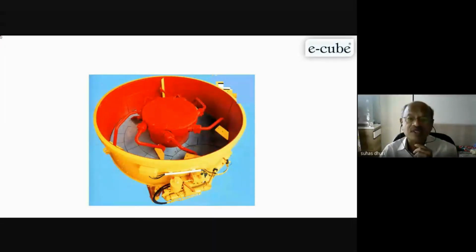And water should reach each and every particle of cement, then only it will hydrate. Otherwise, it will not hydrate. So mixing is important in this. You'll find here a number of blades. This is a scraping blade.